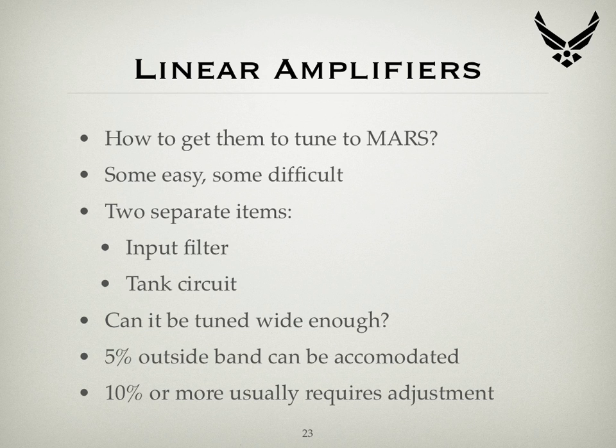And that gives you quite a good way of eliminating harmonics. Now the difficulty is, can the tank circuit be tuned across wide enough a range to allow you to make use of the appropriate M.A.R.S frequencies that will be outside maybe your 80 meter amateur band. Now typically if you're talking about a M.A.R.S frequency that is within 5% of any amateur frequency, it's pretty easy to actually accommodate that frequency by simply just tuning things, and everything will work fairly straightforwardly.